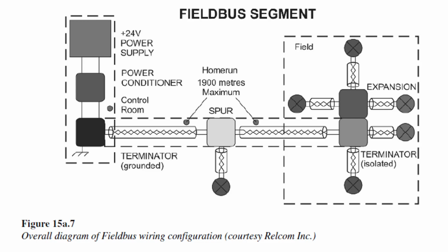This does say also a standard power supply cannot be used to power a Fieldbus segment. All right, and that's because of its low internal impedance. So again, I have some specialty equipment going on here. So just something to think about when you're playing with anything for networking.